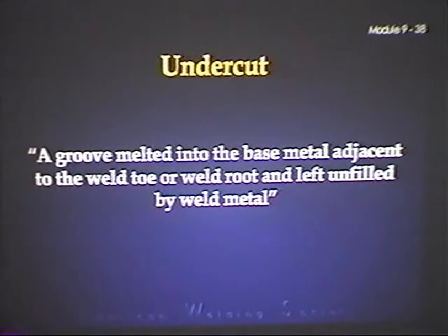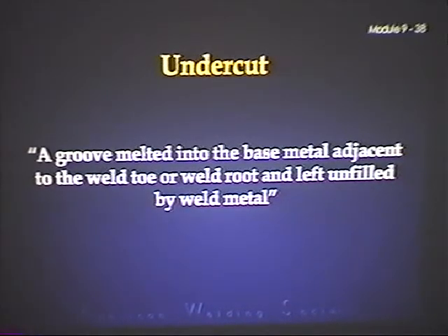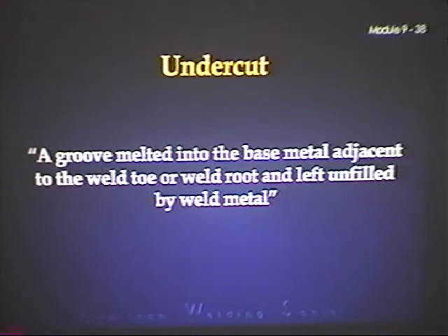So, reading from your book here, it says, because the parent or base metal is much cooler than the weld metal, solidification progresses from the fusion line inward. For this reason, the center of the weld is at a higher temperature than the remainder of the weld while it cools. The mechanism of restraint cracking can be illustrated again by resorting to an imaginary situation as seen in figure 13.2. Basically, let me draw a picture here.